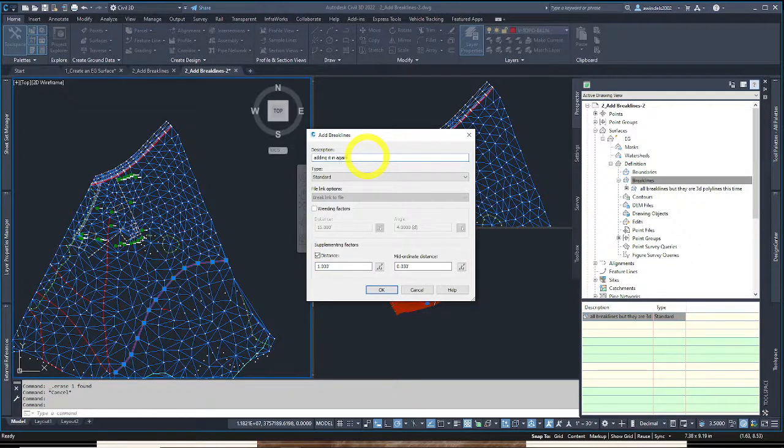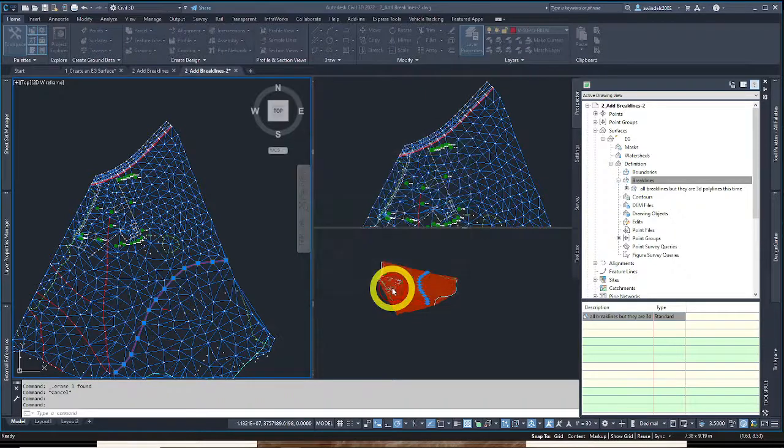It might not work this way, but this is just saying every 1 foot. This is saying on the curves it has to go, let's say, every 1/10 of a foot along a curve. None of these are curved break lines, but if there were, it would form triangles. TINs are only straight lines, so sometimes if there's a curve, an arc break line, you need to make it triangulate more on it to simulate a curved surface.